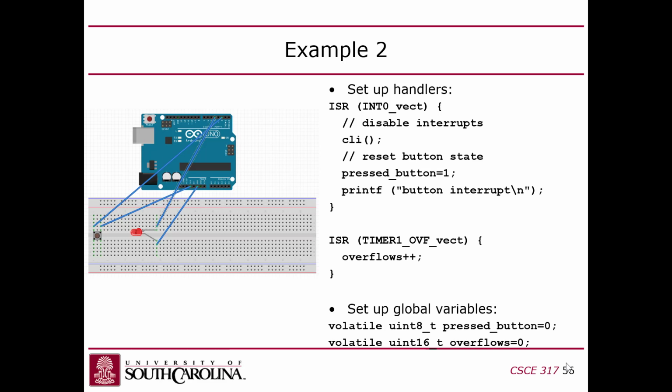So it's a 16-bit timer. You will not be able to hit the button fast enough to keep the odometer on that thing from rolling back to 0, right? Because it'll happen within 65,536 divided by 16 million. It's a very small amount of time.